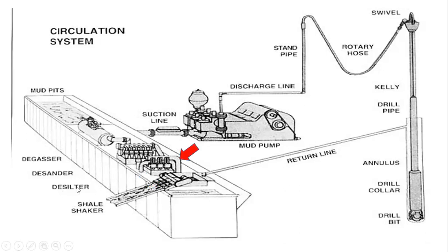Now, silt is a smaller rock particle, of, let me say, a size like a normal average stone you see outside. So this component here, where the red cursor is blinking, helps to remove the smaller rock particles, and then it leaves sand-size particles, okay, within the drilling fluid. And from there, the drilling fluid goes to what we call the desander.